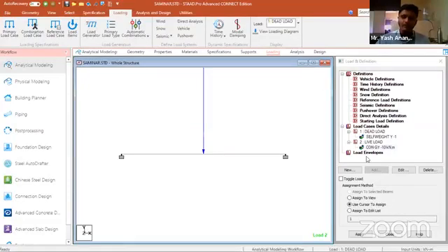Before that, we have to define load combination. After load, what is there? There is a load combination. What we manually do is check the code and see how much the load combination equation is. The dead load plus live load is this much, 1.5 dead load is like this much. But this is nominal. What if we are designing a multi-story building and we have to check for earthquake load and wind load? In manual calculation, it is not possible to check all those load combinations for wind load and earthquake load combined design. There are more than 50 load combinations in that.